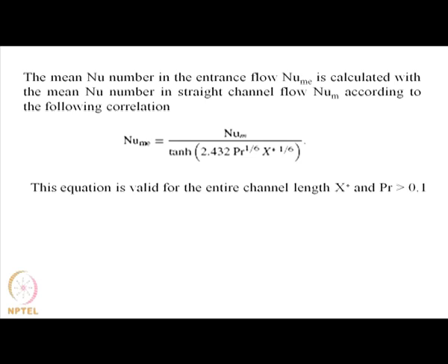We also know that when the flow starts taking place, it's not fully developed, neither hydrodynamically nor thermally. All the relations or correlations that we have so far are for fully developed flow, and for a micro device it may so happen that we reach the end of the channel before the flow gets fully developed.